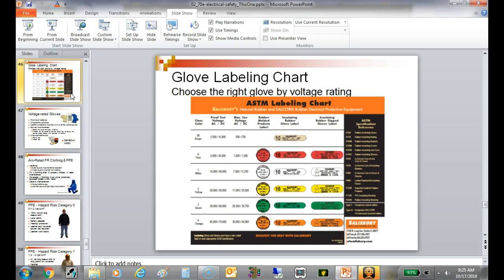Do we wear leather gloves when we walk around and get a static charge? No, because there's just not enough energy. There's no current available to that voltage. As soon as I touch you, it discharges, right? So it would still be a category 00. You understand? There's a lot involved in calculating this.